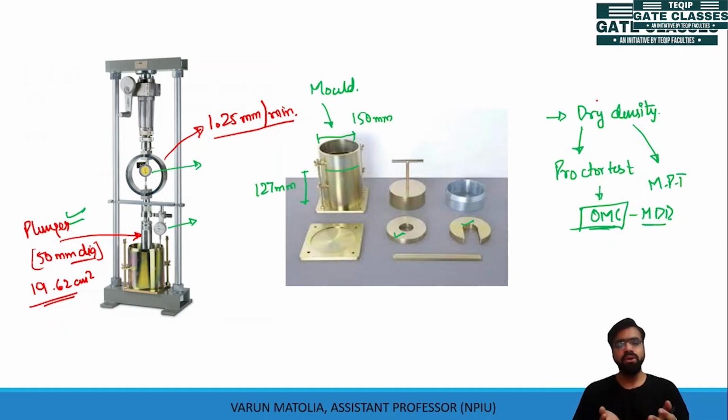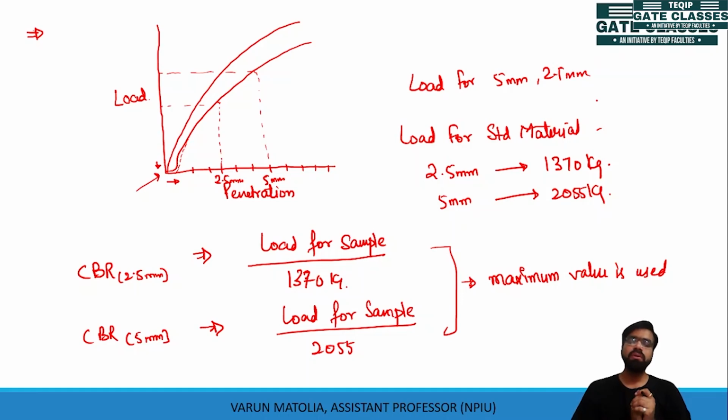We calculate the load and the settlement or penetration. This load penetration curve is made and the load at 2.5 mm penetration and 5 mm penetration is calculated.